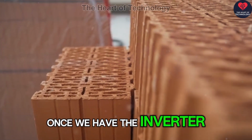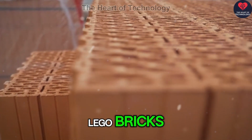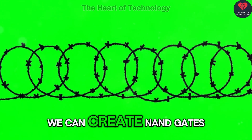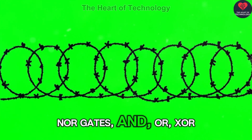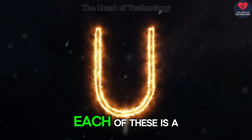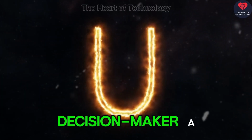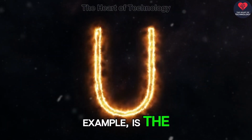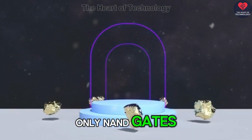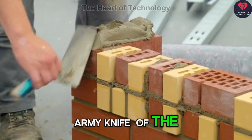Once we have the inverter, we can start building bigger Lego bricks. By rearranging our N-type and P-type transistors, we can create NAND gates, NOR gates, AND, OR, XOR, and XNOR gates. Each of these is a slightly different decision maker. A NAND gate, for example, is the universal gate. You can build any other gate using only NAND gates. It's the Swiss Army knife of the CPU.